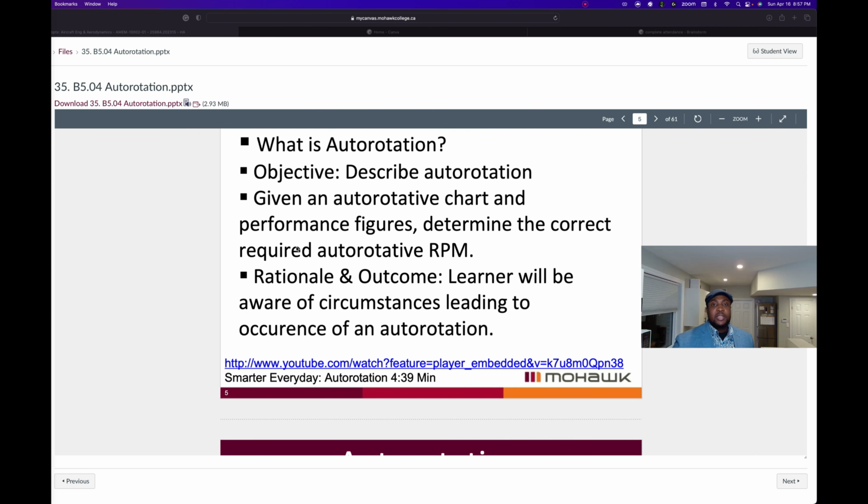So ground resonance vibrations are not uncommon for helicopters because we have large rotating bodies. Vibrations can occur on the ground in fully articulated rotor heads. In a fully articulated rotor head system where we have lead and lag happening, sometimes you can have the blades bunching up together. This means that, say, blade number 1 is leading while blade number 2 is lagging.